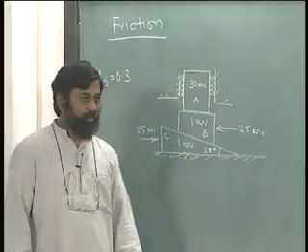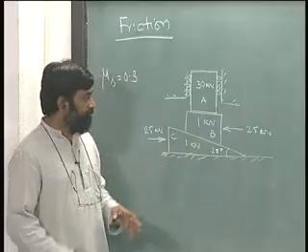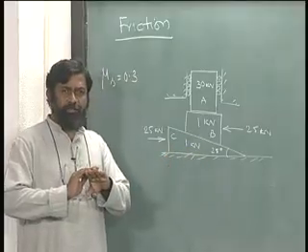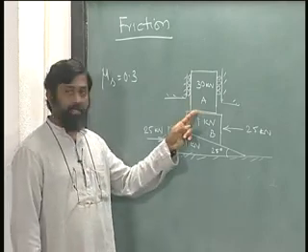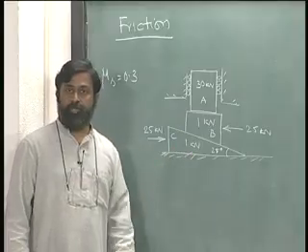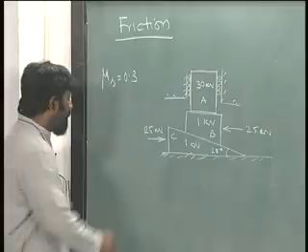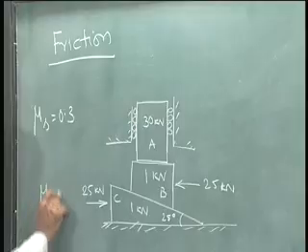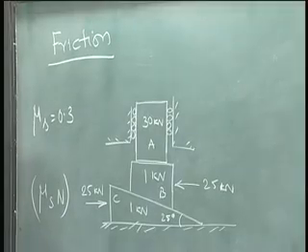So looks like there are a few problems that we have to handle here. Supposing I consider purely statics, what happens? There will be some force over here, there will be some force over here, there will be some force over here, which is a frictional force, but not exceeding mu s times the normal reaction that comes on each one of these blocks.